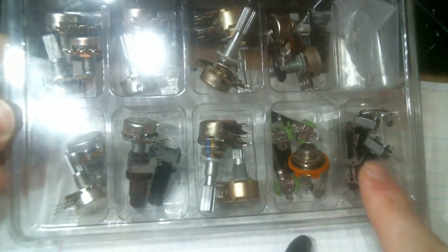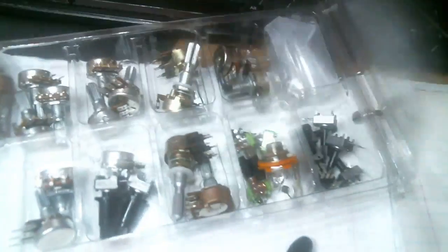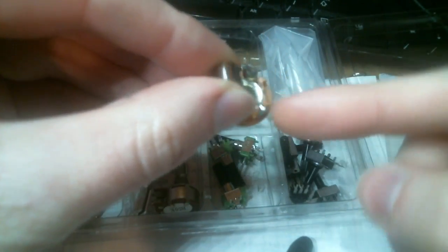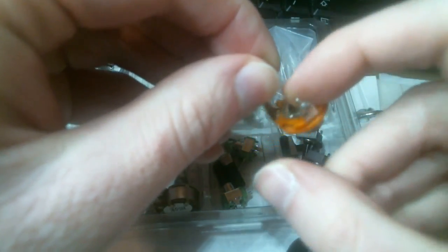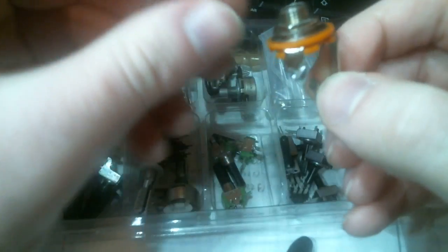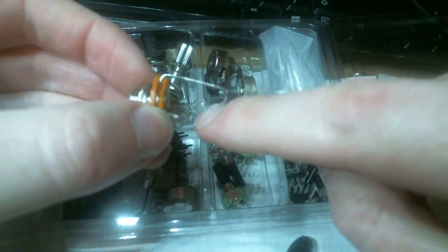So you have tiny ones here. These are 10K. These are 100K. This is an input on a guitar. So you see this part, and you plug in there, and you're connected to ground and live. Now you can tell as ground is right there, which goes around the body of a quarter inch plug, and this goes in this ring in the center of these orange, comes up here and presses against the tip.